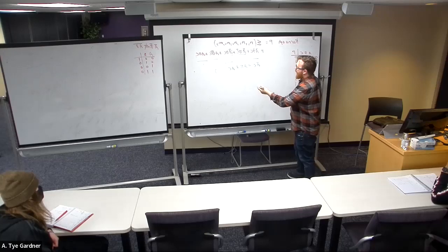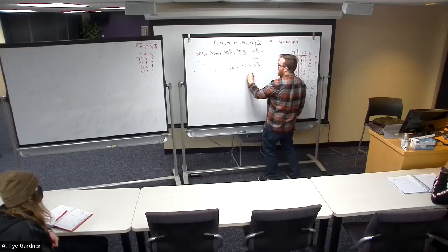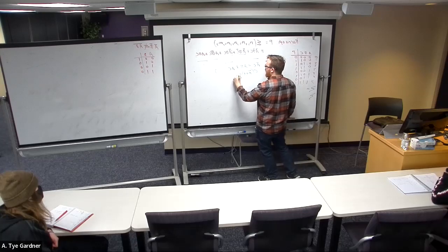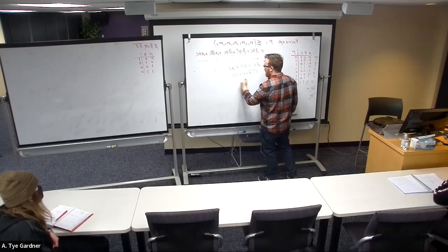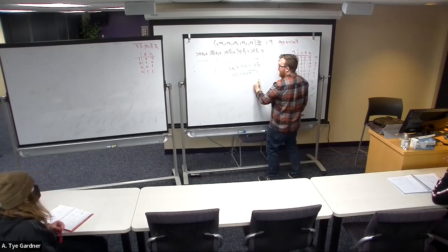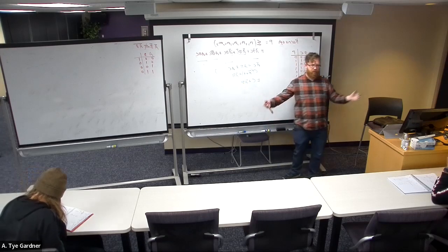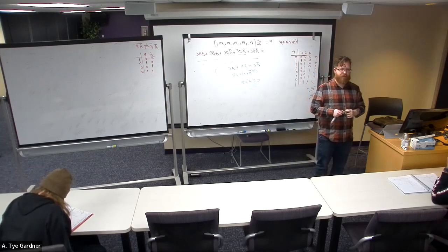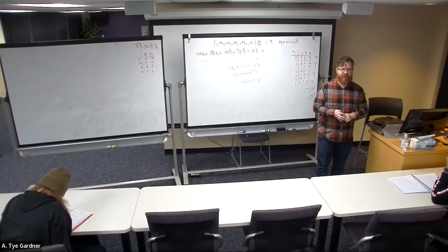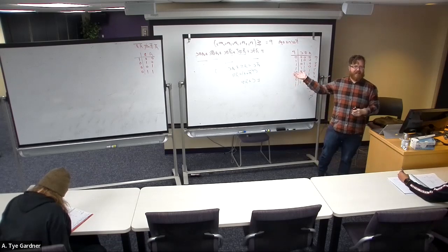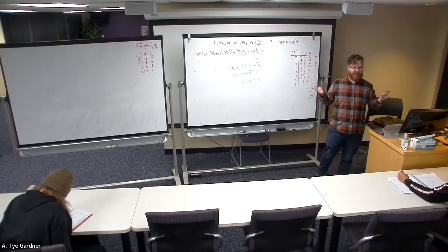So now I have that, and now I have this. That goes away, which is C or not A, B. We're good. We've simplified it, right? That's Boolean algebra. Logic adjacency is a wonderful thing. Starting with sum of products makes Boolean algebra very, very easy. When I don't start with sum of products is when it's harder, right? Because then you end up doing things like De Morgan's theorem.